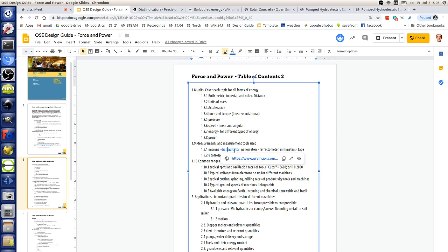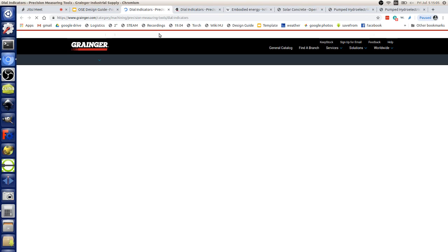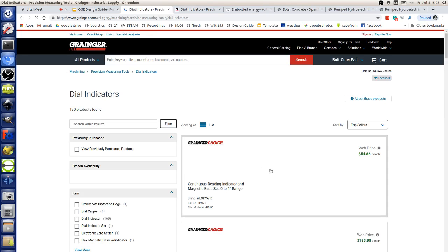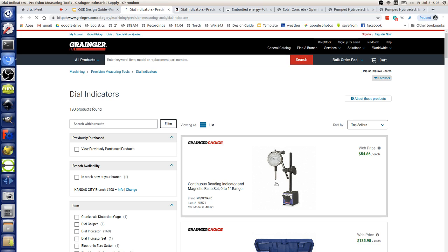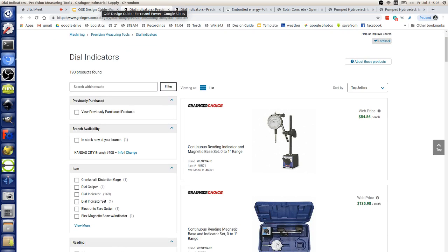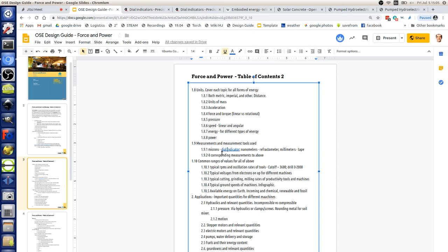But dial indicators, what's a dial indicator? It's a device that looks like this. It's a very precise thing that has a little indentable structure, a little poker, and the distance you poke it shows up on a dial. These things are accurate. You can clearly see thousandth resolutions. That's pretty much as crazy as we get currently to get precision machining happening. Beyond that, I don't know yet what happens. If you go to measuring microns, like with air bearings, how do you measure that? That gets to the next realm of technology.